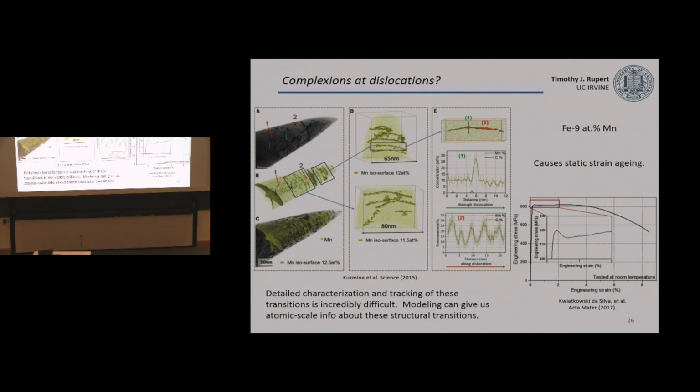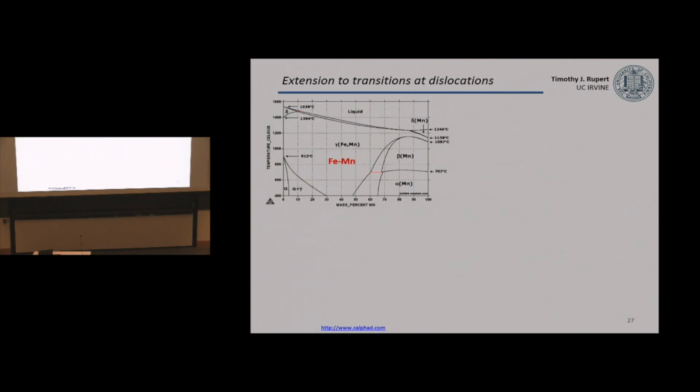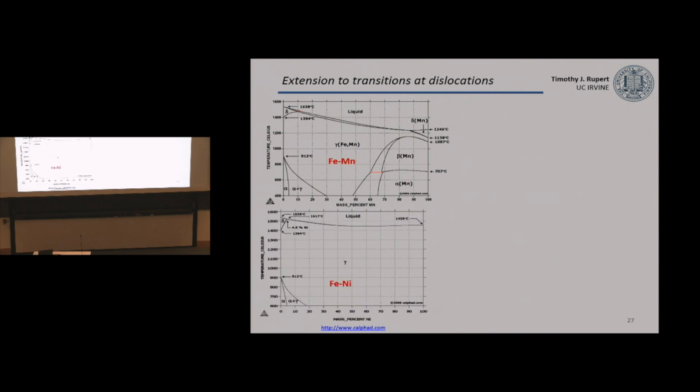We wanted to do atomic scale modeling to understand how these transitions happened. Now, one downside of atomic scale modeling is you're limited by the potentials you can use for molecular dynamics and tools like that. Turns out, they studied iron manganese. We didn't have that. There isn't a potential. If you want a potential, you can spend 3 years discovering it, or you can be creative and look for a material system that's kind of similar and has some of the same aspects. So we found a nice potential for iron nickel. Turns out that this part of the phase diagram where we're working looks very similar.